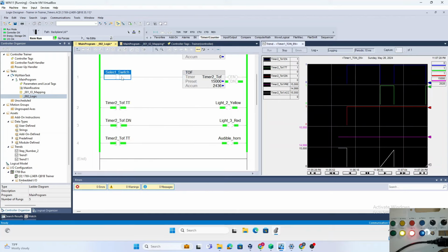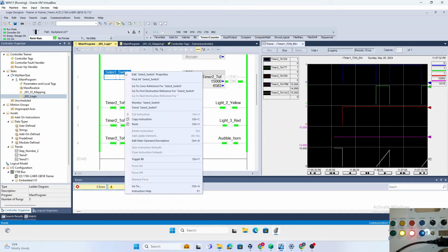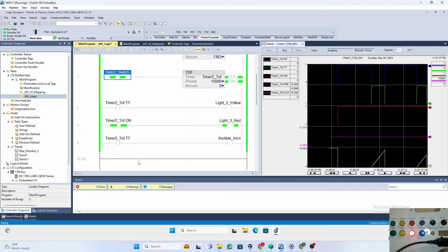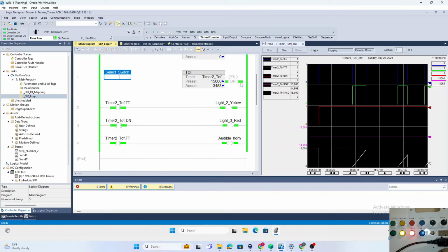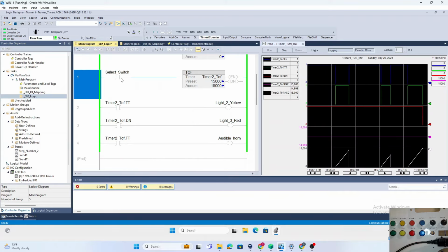Once the input condition is off, the done bit remained high. And while the timer is timing, if we toggle the input condition back to on, the done bit stays high and the enable bit also goes high. And if we toggle it again, the done bit is high. So that's the purpose of timer off, it's when you want something in the system to stay on for a longer time than everything else in the system.